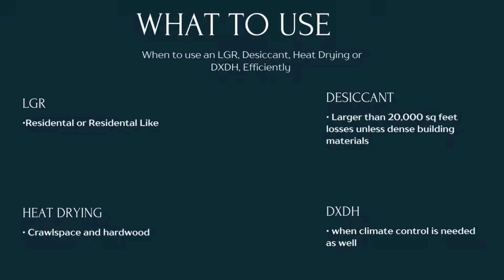You cannot over dry hardwood with a desiccant dehumidifier or an LGR. You're not going to get that much heat on it, and not going to get it done like that. So some people like to tent hardwood floors so they have less area to dry. It's fairly expensive, and I've found it may be just as expensive somewhere just to add another desiccant, but again, it depends on your situation.